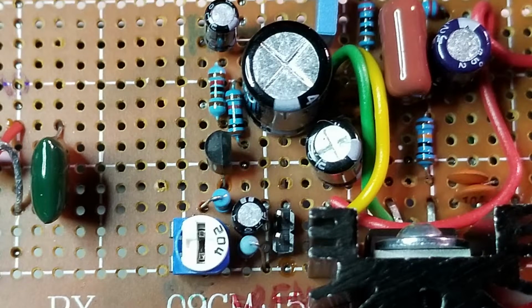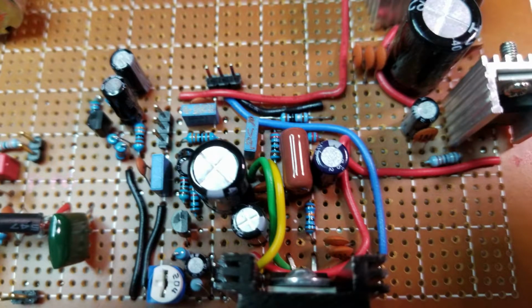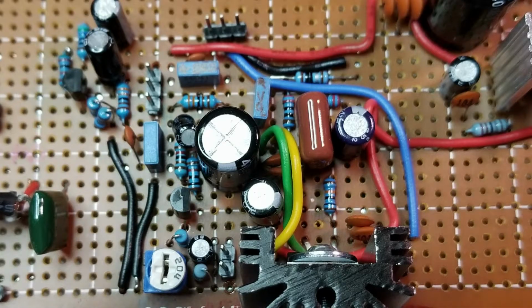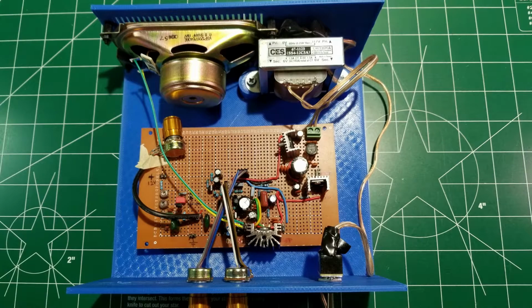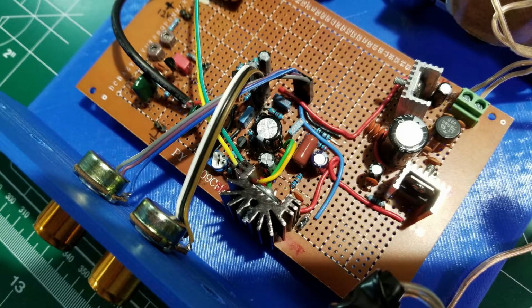Easy to see is the trim-pot RV1, which is located at the center of the lower edge of the board. Right above is located the transistor of the first stage of the preamp, whereas the second stage transistor is located on the upper left of the area, close to its polarization resistors and a couple of electrolytic capacitors. Also visible are the two 3-prong connectors used to attach the brightness and volume potentiometers. And finally, here are a few overall views of the final assembly positioned within the Theremin box, where you can see how the two potentiometers are connected.